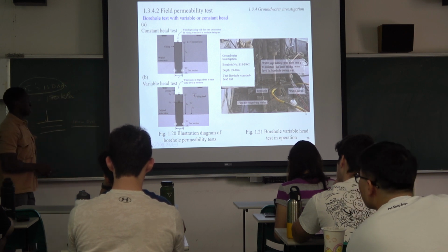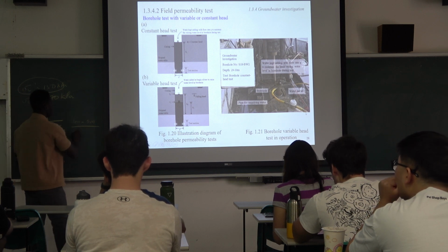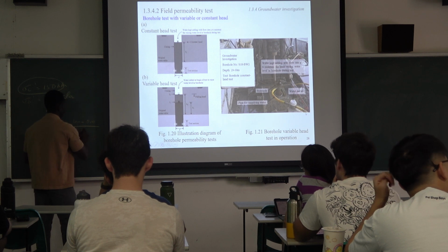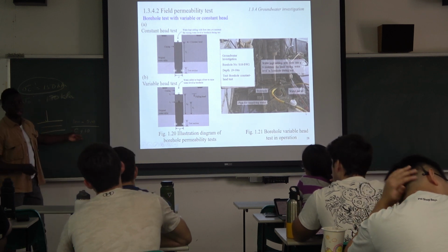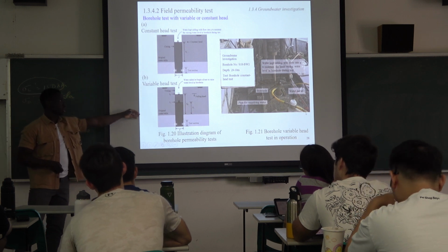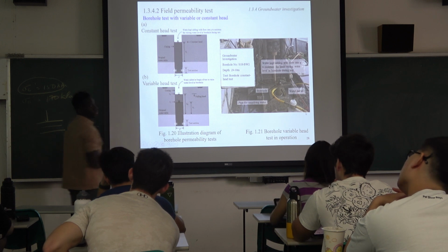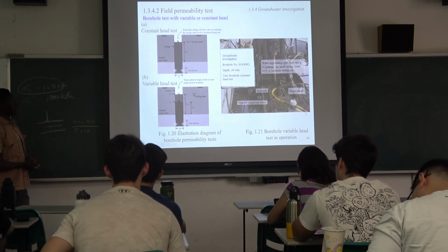So your time 0, the initial time, let's say, assume that this is just 0, and the time it takes from here to here is about 10 seconds, but you still need to keep this positive. Then you just minus, and you get meters per second. So that will give you the permeability or the hydraulic conductivity of this layer of soil, like how quickly water flows through it.